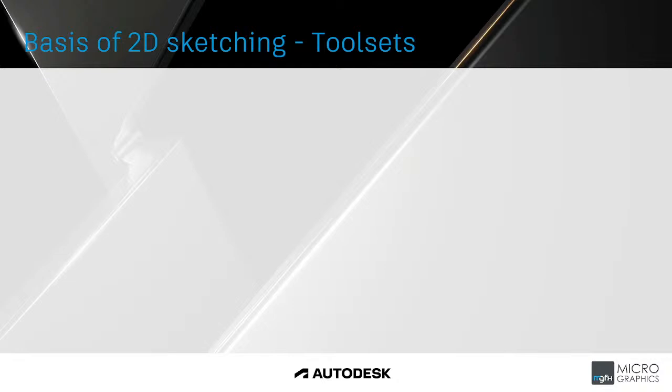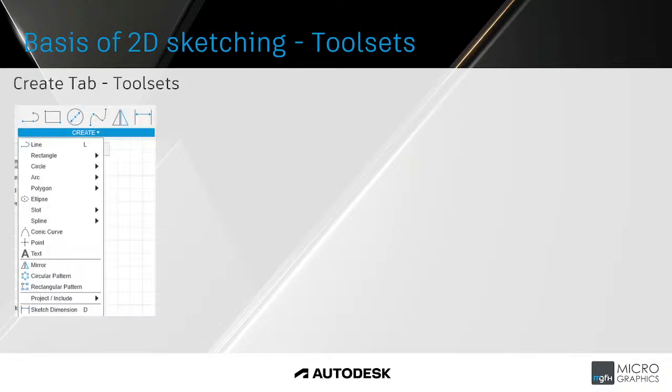When the plane has been selected, you are ready to create your sketch. So under the Control panel and the Create panel, you have different tool sets available. For instance, you've got the line, the rectangle, circular, a slot, and a spline. And you'll see your Create also has a drop-down menu where you can see all the tool sets that are available in the Create panel.